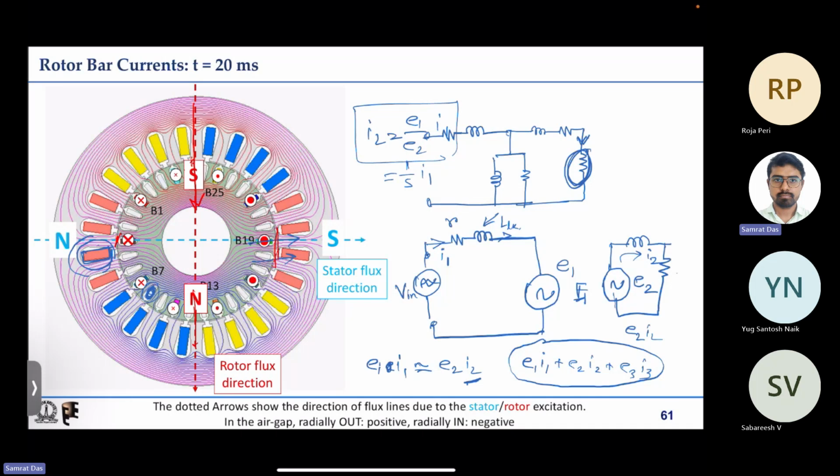That is why those numbers, say 500 ampere, 400 ampere, whatever we saw for some induced EMF and some indicative resistance of the bars, are not impractical values, but are what is expected in the bars of an induction machine.